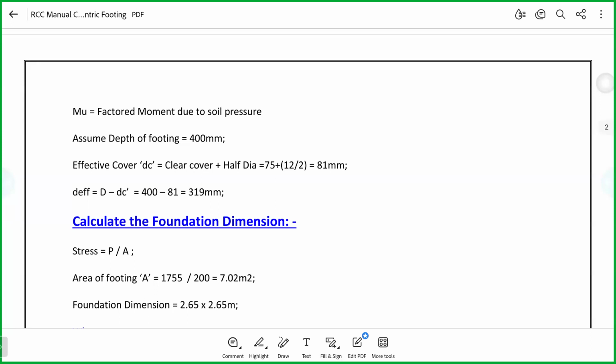The one statement which you said: concrete is strong in compression, weak in tension, so a column is a compression member. Then you don't need reinforcement. Correct. However, we are putting reinforcement in order to have long-term durability, because there could be climatic changes. Due to summer and winter, concrete has two properties: shrinkage and expansion. To control those two, I need the rebar. You get my point. It is very critical. It's clear, right? Okay.